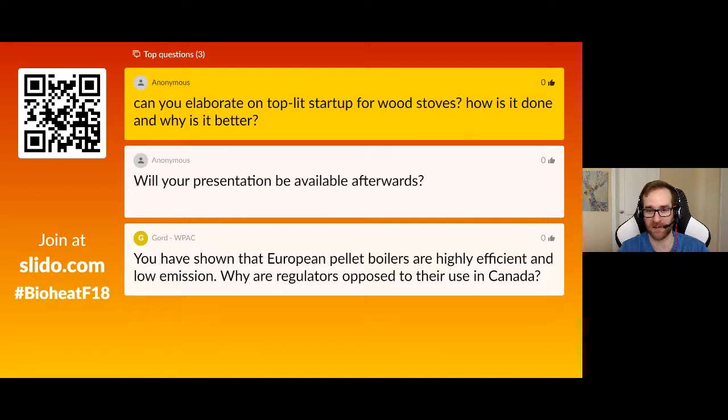The idea is that you get to that hot temperature, proper turbulence, time, and proper air to fuel ratio right away, instead of waiting for the initial phase for the whole batch of wood to be in the proper sweet zone. That's essentially how it's done. It does take a little bit of trial and error to do properly, but it works.